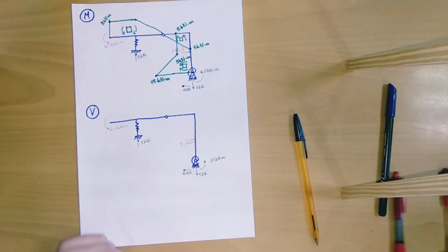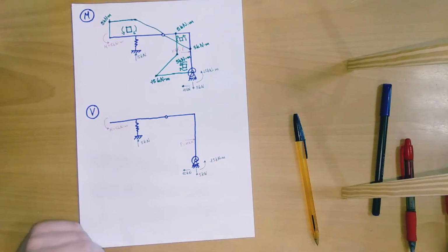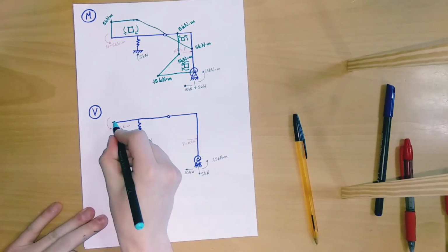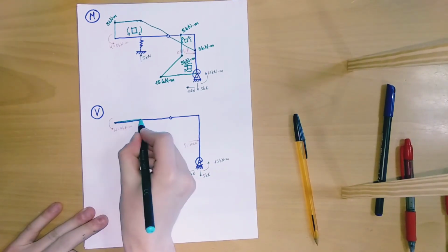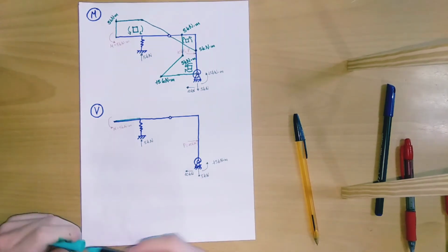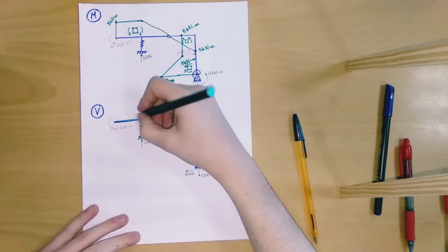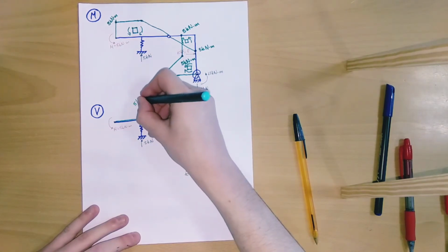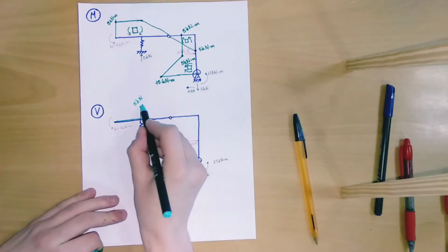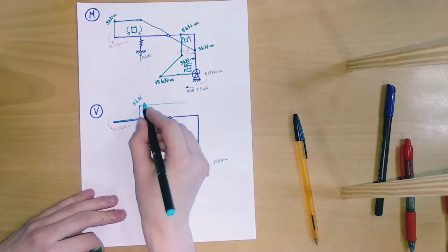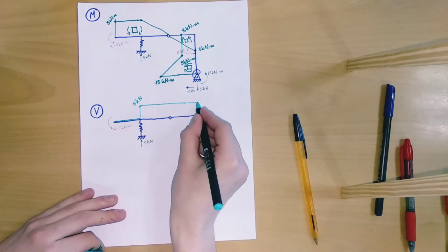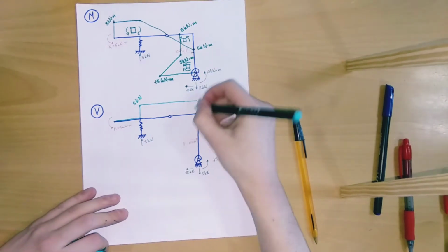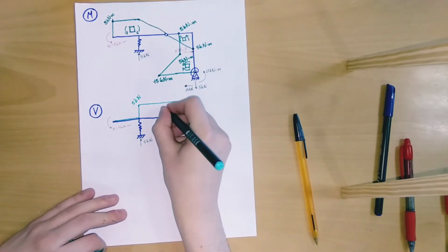Well, as you can see, in this part we've got no forces, so the diagram is going to be 0. Now here we're going to have a jump of value 5 kilonewtons. Then it's going to continue constant till here, where we have a force of -5 going down. So it's going to be like this.